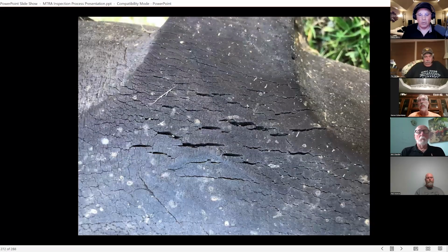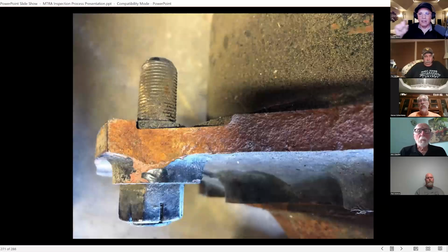But short of that, you will see, oh, I don't have it in here, there are teams that run a girdle. There's a plate that goes on the back side that won't allow that to happen. It's a support plate that attaches to the back side of the wheel studs and keeps that from being able to flex and break off. Yeah, there was a picture of the girdle way back in the restraints section. I don't know that you want to go that far back to find it, but there was one on there.